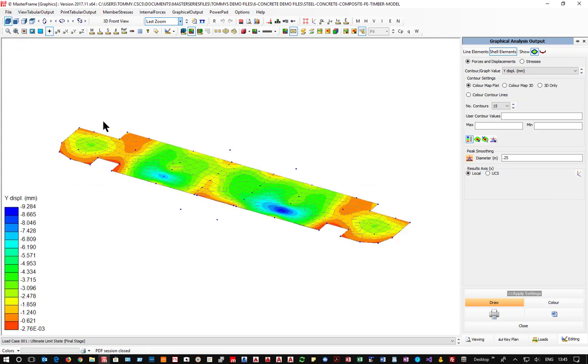So windowed that, and it's taking us just with the FE. So we can see our major displacements here, not so much here, due to those upper columns that have to go through this transfer beam. Now over here and here it's not as bad because we do have the transfer beams in here. It's just the slab doing all the work.